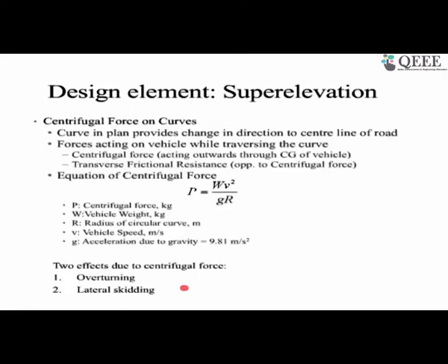Before I go to the next slide, there are questions about what should be the minimum width of median and shoulder in national highway. For the shoulder, I think for the national highway they say about 1.5 or 2 meter, something like that. I'm not exactly sure, you can look into the IRC code and that value is there. About the median, generally they prefer about 10 meter, depending on future improvement, and minimum they can go up to 2.5 meter, something like that.